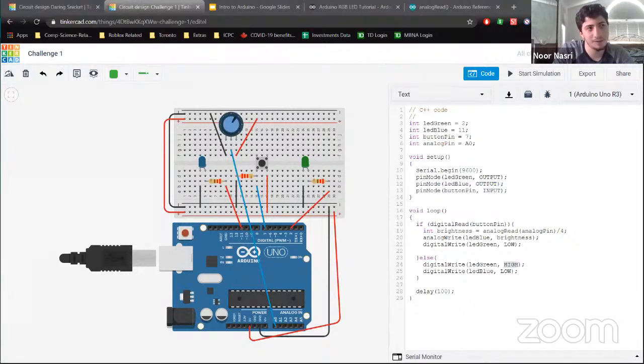The biggest thing I was doing is, for some reason in science class, I was thinking of negative as the charge, so I was thinking it goes backwards. So I wired pretty much everything correctly, but 100% backwards. It would be negative going to positive, which wouldn't really matter until you had diodes like this where it needed to be an anode and a cathode. And you wouldn't really notice the difference until it started ruining things.